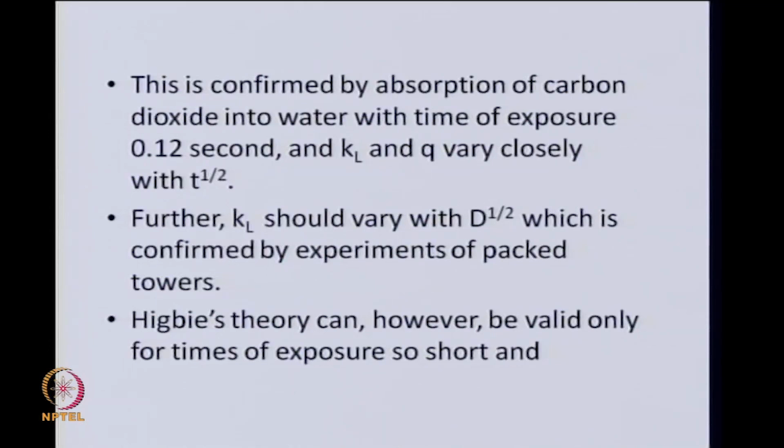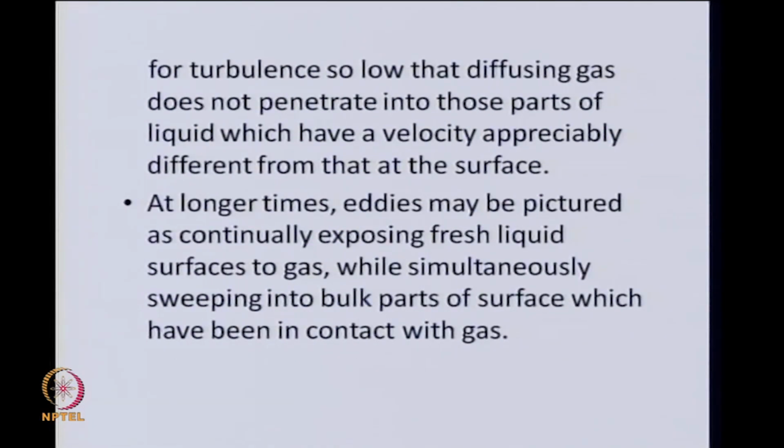But again, Higbie's theory can be valid only for very short exposure times and for such turbulence that the diffusing liquid is not able to penetrate deep within the liquid, where the velocities may be appreciably different from the velocities in the surface.